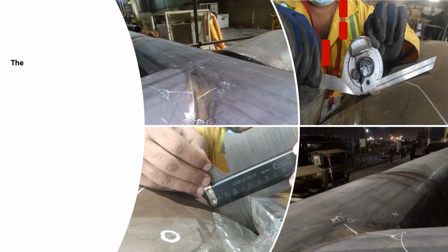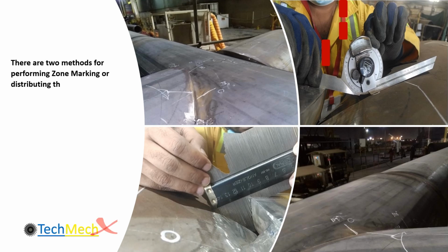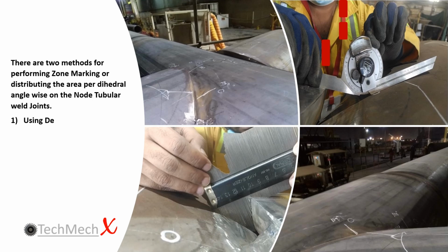There are two methods for performing the zone marking, or distributing the area per dihedral angle wise, on the node tubular weld joints. Number 1, using the degree protector or contour profile gauge. Number 2, applying the graphical depiction provided in AWS D1.1 Annex 2.